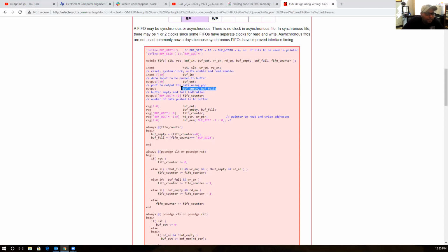Also, the empty buffer and full buffer, in the drawing that we used in the tablet now, we said those are the flags, and flags mean they are outputs. Do you guys agree? And because they are outputs, basically they also have to be registered, because they have to store data.